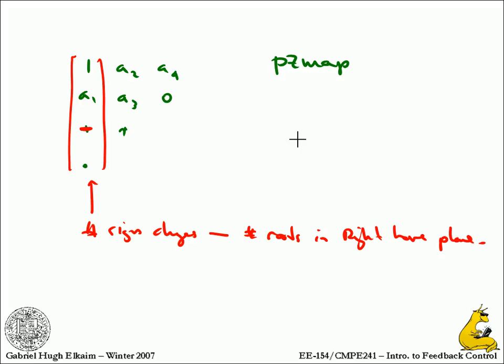However, if you've got something that has a gain in it somewhere in that characteristic, then you've got to do something a little bit different. Can you still use pzmap in that case? With the gain, symbolically, I don't know. I don't think so. I mean, you can assign the gain. That's getting into root locus, where you give the parameter of variation and see where the roots move as that parameter varies.